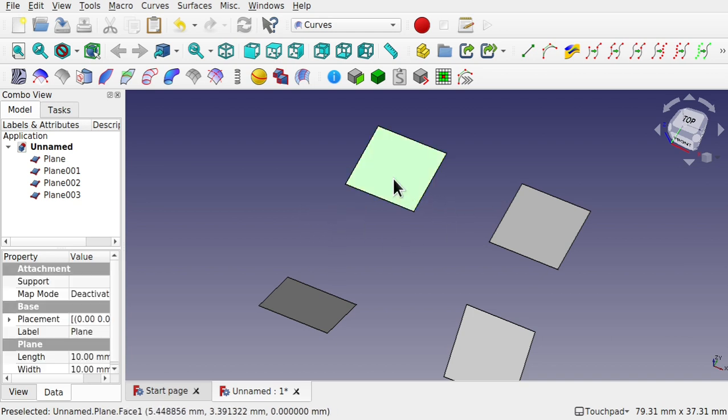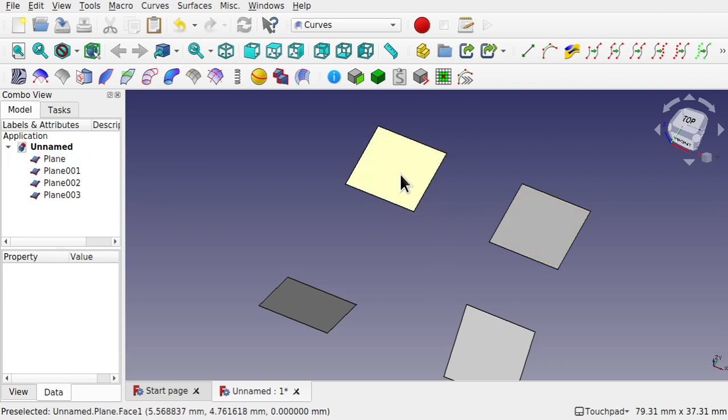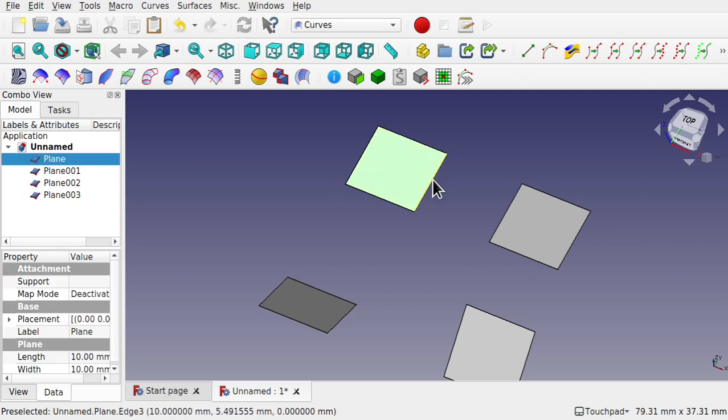So you select the face first, and then the edge you want to use for the connection. So it will use this face to shape the surface between the two objects. And it will use this edge as the connection. On this side, it's where you want the supporting surface to go. Control click, so control click these two. So first the face, and then control click the edge. Still holding down control, we'll then select the face on the other side and the edge.